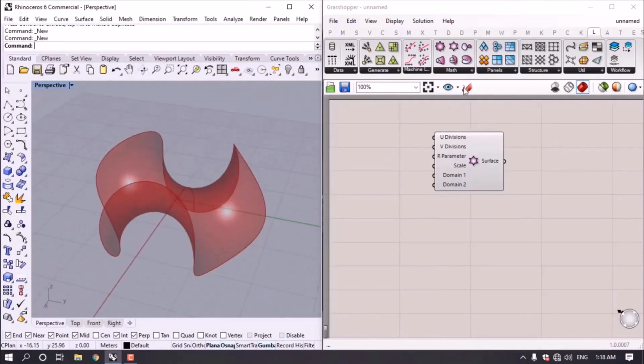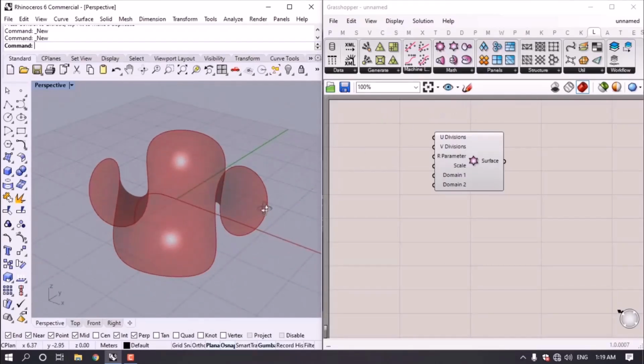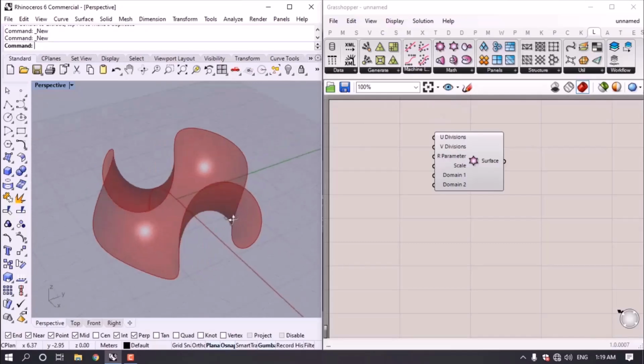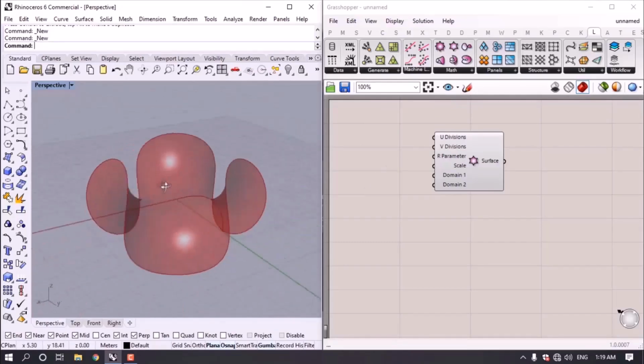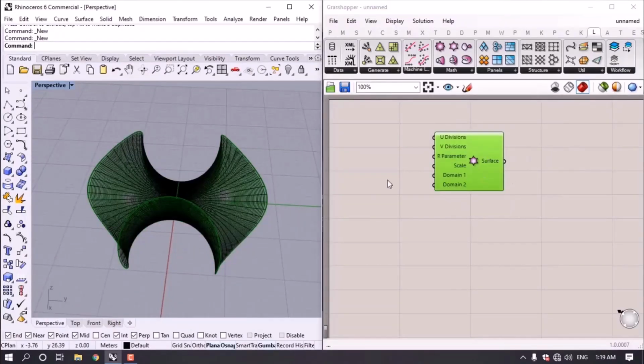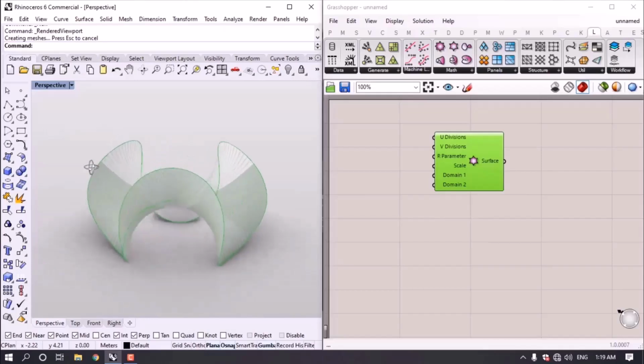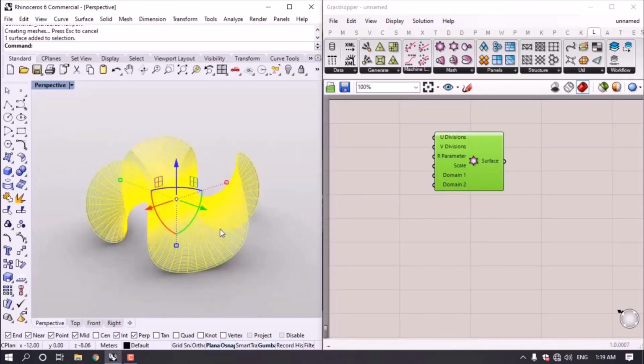So as I told you before, in the Math tab, here we are given some prepared geometries. Check it out. You can just open the Math tab and then select the intended geometry, so then we can have it in the scene in the perspective view. And then if I bake it, check it out. Let us check it out in the shaded viewport, or rendered viewport actually, this way.